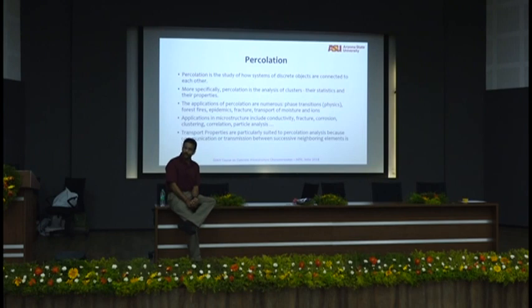Whether it's moisture going into concrete, whether it's chlorides going into concrete and corroding the steel, whether it's sulfates going in from the soil and creating sulfate attack and destroying the foundations, whether it's alkalis going in, all of these start with percolation. So whenever you talk about the pore structure, it's important to characterize the percolation threshold of that system. And I'll tell you what the importance is. It's an extremely important characteristic.